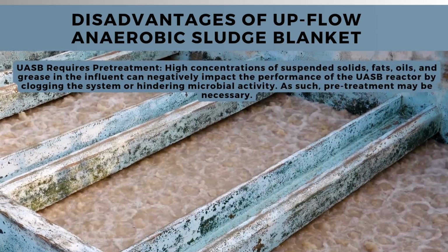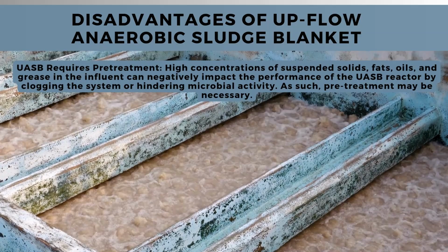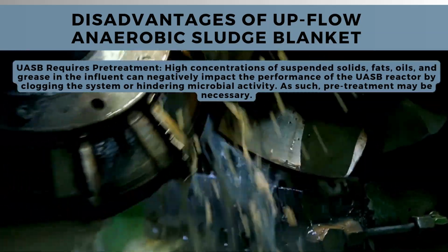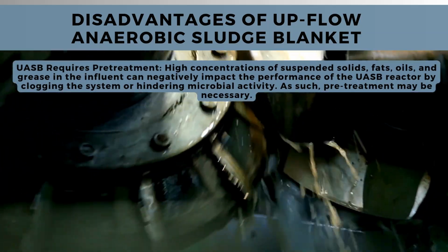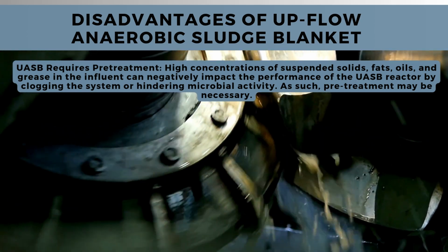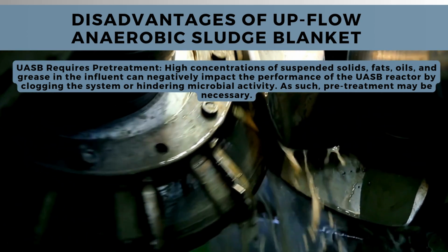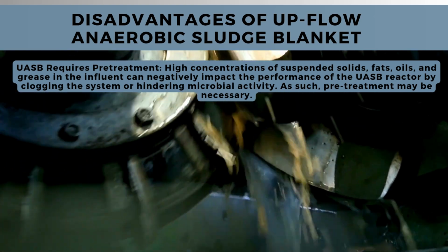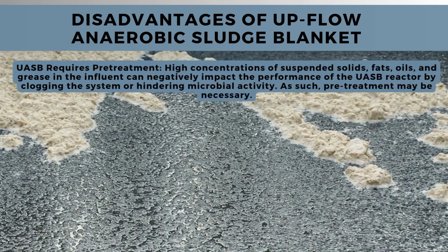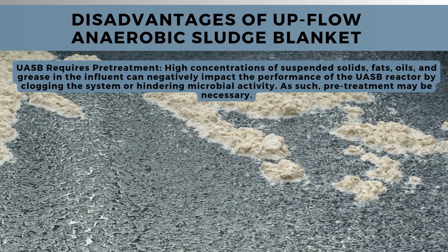Also, it requires pre-treatment. High concentrations of suspended solids, fats, oils, and grease in the influent can negatively impact the performance of the upflow anaerobic sludge blanket reactor by clogging the system or hindering microbial activity. As such, pre-treatment may be necessary.